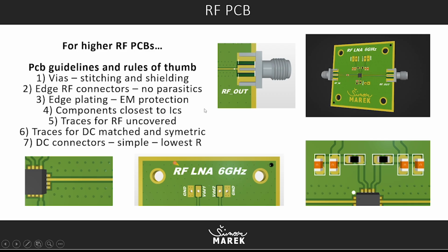Via stitching and shielding, etched RF connectors for lowest unwanted behavior and parasitics, edge plating, components closest to ICs, and traces uncovered.